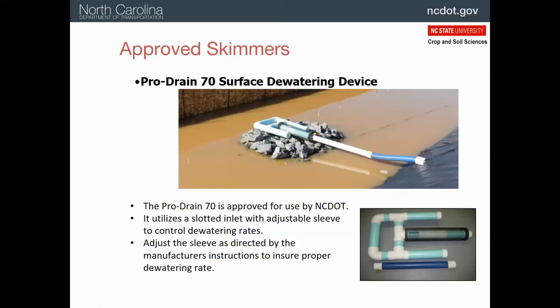Secondly, having a standing pool actually increases the efficiency of the basin. So when water comes in filled with sediment, it hits a standing pool, and that actually acts as a brake. It slows the water down very quickly, and it drops out a lot of sediment that way.